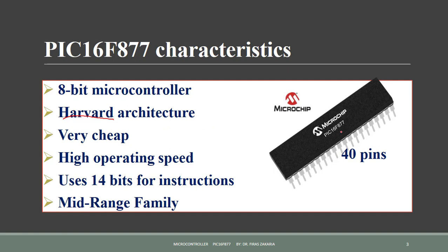This PIC16F877 belongs to the mid-range family. It has high operating speed and it uses 14 bits for instructions. This is the figure for the PIC16F877 chip. It has a total number of 40 pins and there are 33 pins for input and outputs.